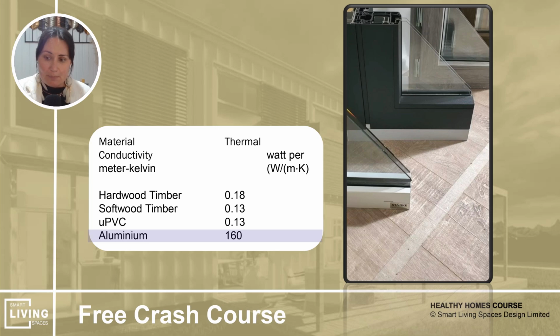Now, I just want to bust a myth here. Double glazing doesn't stop condensation on your home or in your home. It might reduce the condensation on your windows in winter, but glass doesn't remove moisture from your internal air. Ventilation does. So if you're double glazing to stop weepy windows, there are other things that you need to consider, because that condensation will still just keep happening. It's just not happening on your windows. If you don't have ventilation, it may well be happening somewhere where you can't see it.